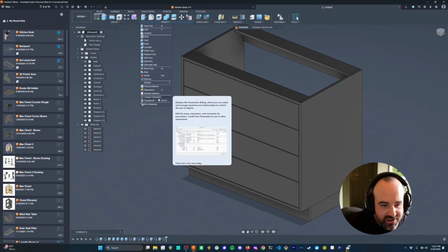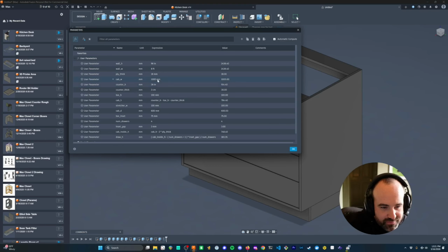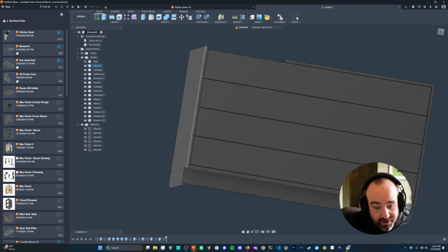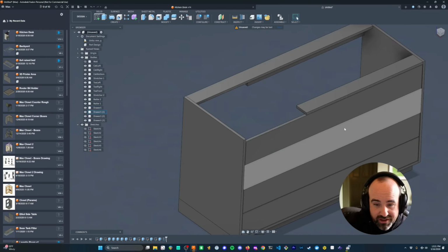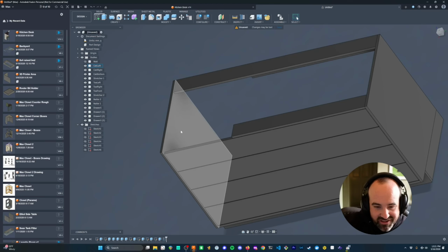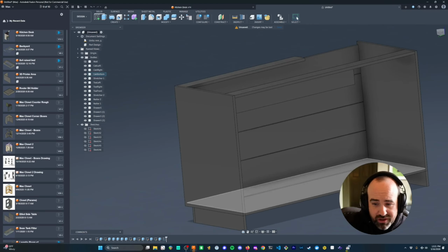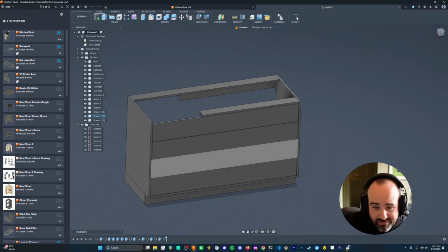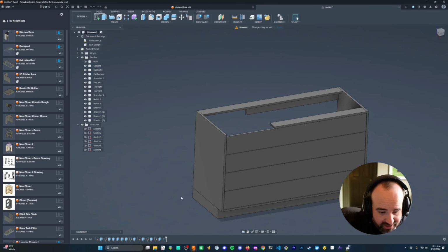And so if I change a value here, like the cab width to like 1500, it's probably going to break. A lot of it worked, but these stretchers clearly were not properly constrained to this edge. I think they were, when I got lazy and I did the extrude and I clicked on this, it just used that value, the distance. It didn't actually constrain it to the edge. So there's some work to do if you want it to be truly flexible based on changes there. For now, we don't need to do that. I can always go back and fix it.